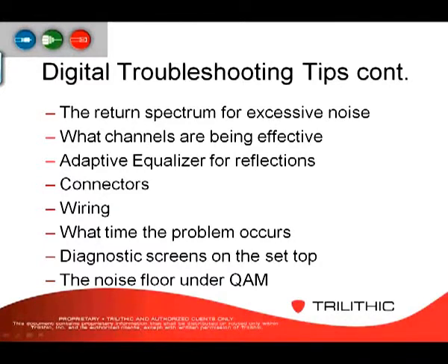on an individual QAM carrier. So if you're having a problem with HBO East, and you know that on that same QAM carrier there's HBO West and there's ESPN or whatever else is combined with it, then you want to check those other channels as well. That'll point you to whether it's an actual problem with that particular QAM carrier, or something with just that particular channel that needs to be addressed in the headend.